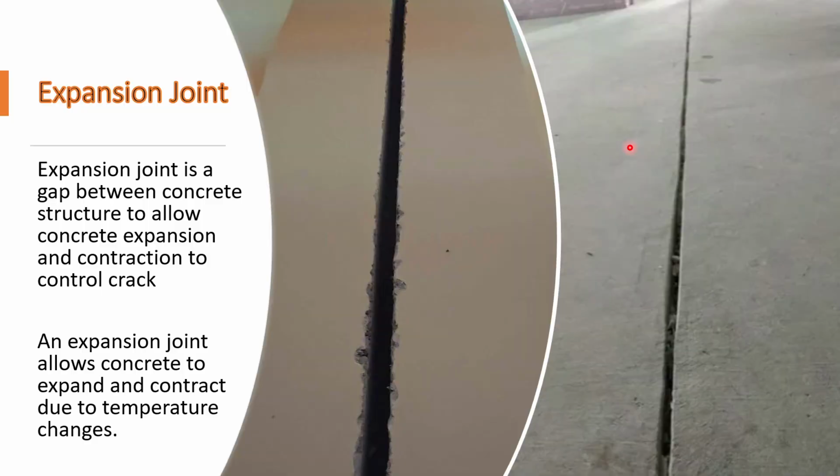Now move to expansion joint. An expansion joint is actually a gap between concrete structures to allow concrete expansion and contraction to control cracks. Sometimes we have very long and lengthy buildings, so we have to ensure that there is no crack induced by the thermal contraction and expansion of concrete and rebar because of thermal changes. So we split our building into two to three portions through expansion joints, as required, to ensure that there is no crack induced because of the thermal contraction and expansion due to thermal changes.